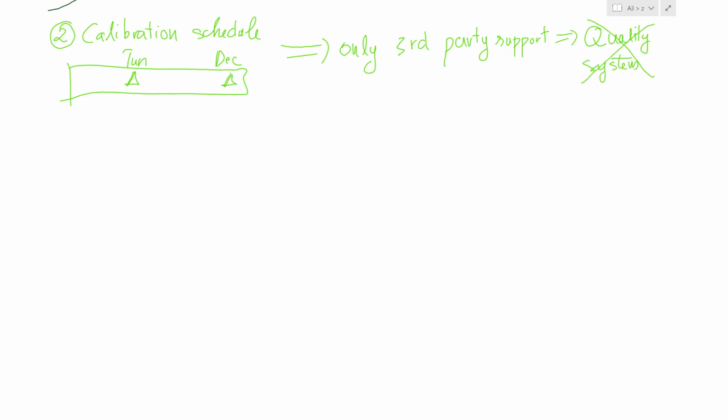Now you can see that if you calibrate only 2 times per year, in June and December, it means the other months still have a high risk rate. So with a good quality management system, we will not wait until everything becomes NG. We need to check and verify your machine daily or hourly, or maybe before you start your work.